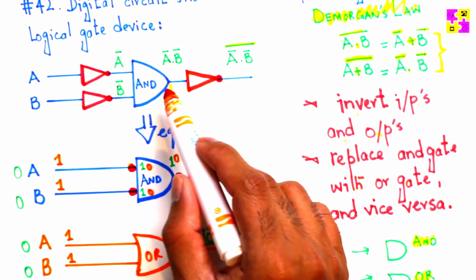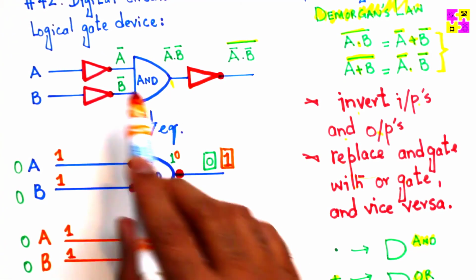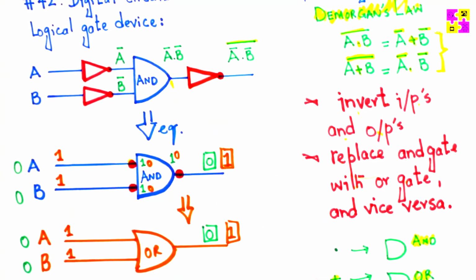So this gate can be replaced by a 2-input OR gate. Very simple. And it will help you get rid of the 3 inverters. That means fewer transistors on your circuit. Switching speed becomes faster, size smaller, save on cost.